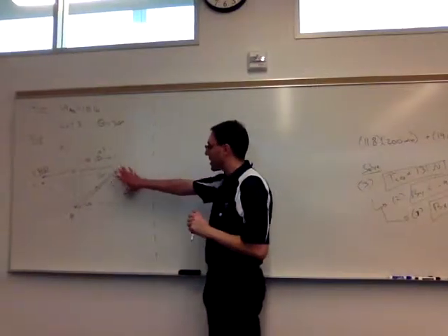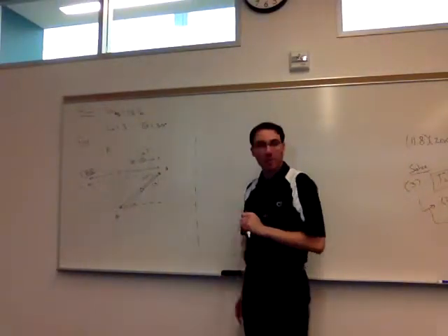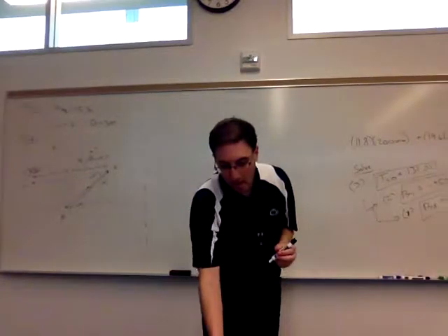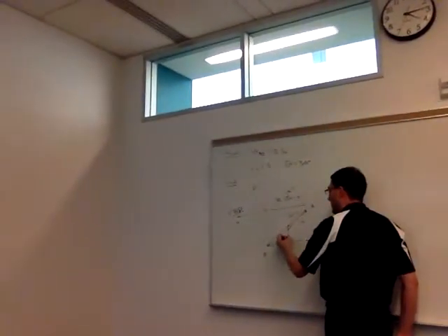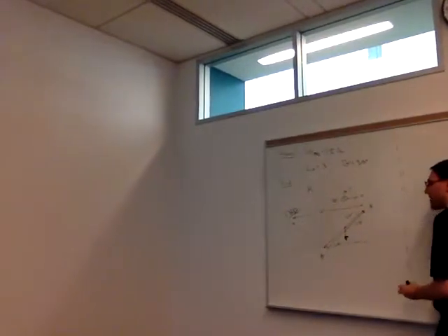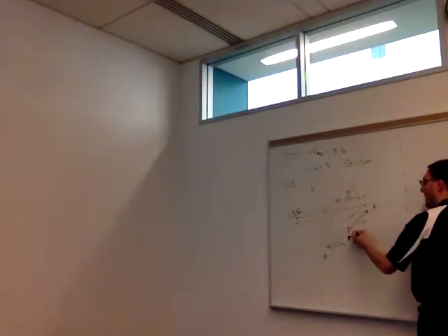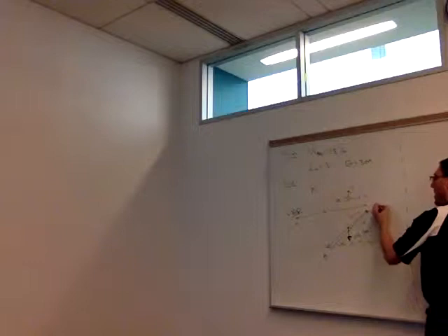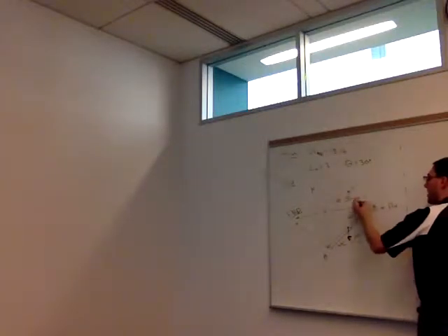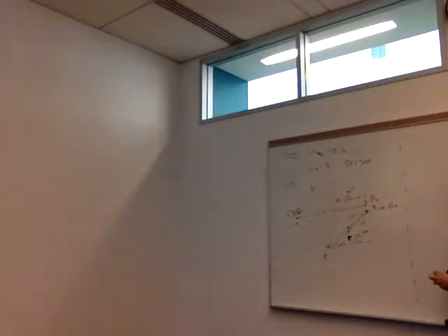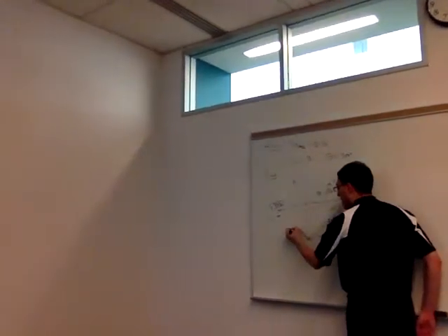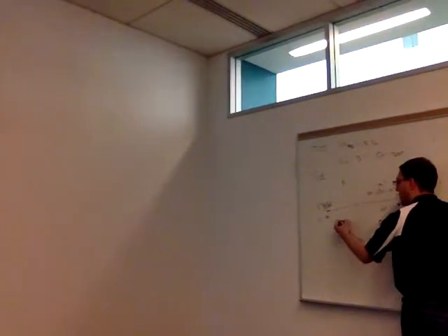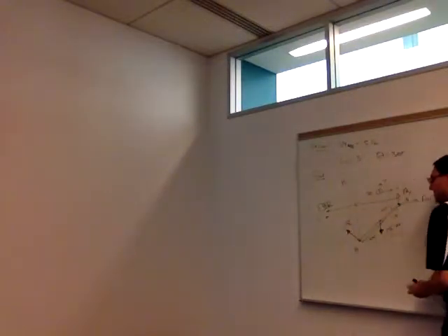All right, so here's kind of the skeleton of the problem. I just have my object. So the forces that are going to act on it: we do have to include, in this case, the weight of the rod. Since it's uniform, it'll act at the center, 15 pounds. We have that pin connection at A, so we'll have an AY and an AX. And at B, if we're disconnecting it from the spring, we'll have that force in the spring, which I'll call FK.